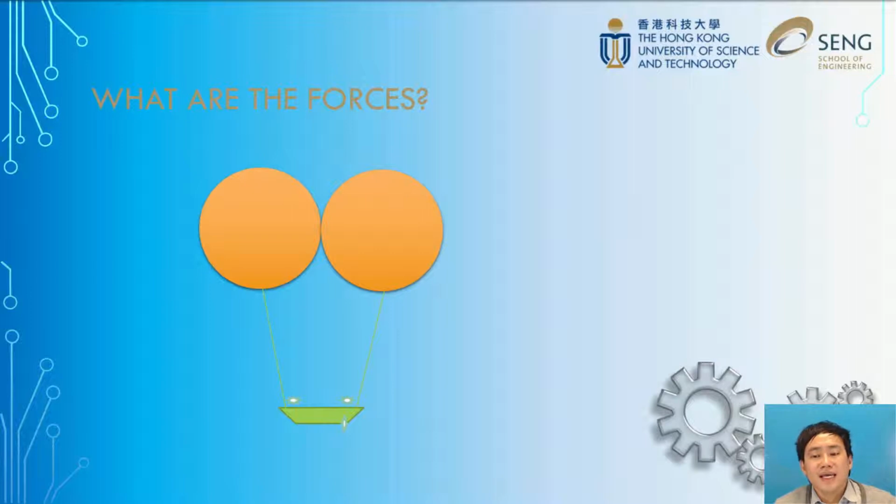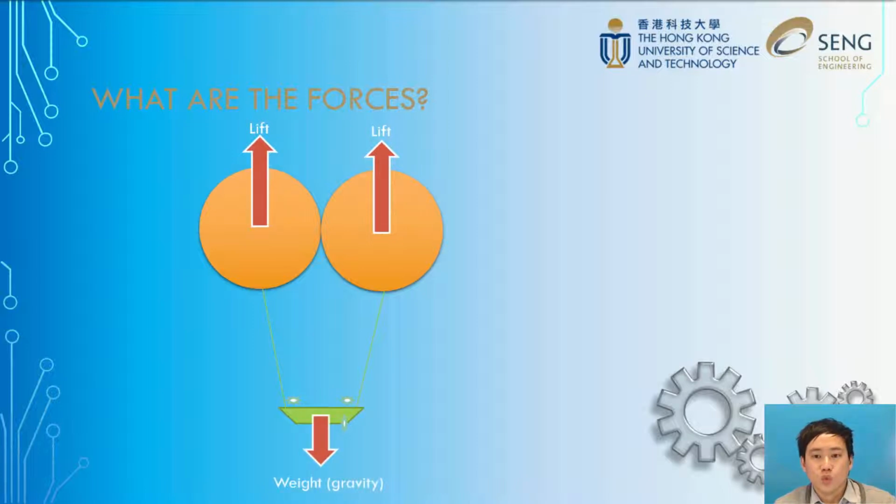So let's come back to the airship that you're going to build in this course. The typical forces acting on the airship body are the lift force due to helium balloons and the weight of the airship body. The motors and propellers will generate lift forces for taking off and thrust for general movement. With translational movement, there will also be drag force caused by the air particles.